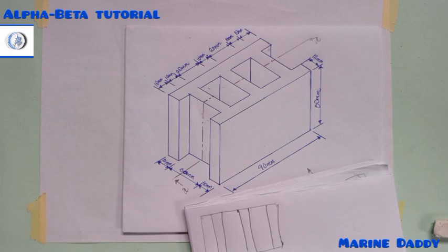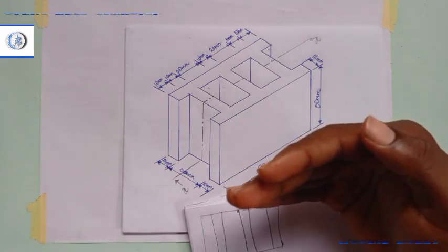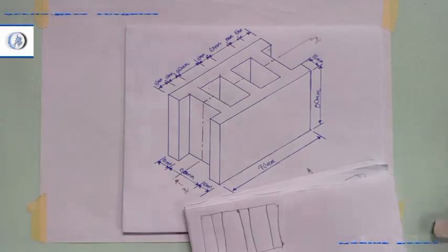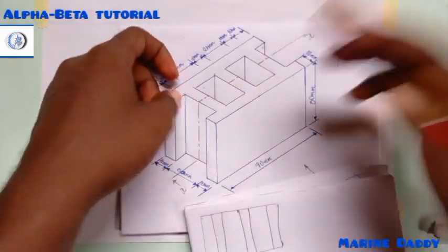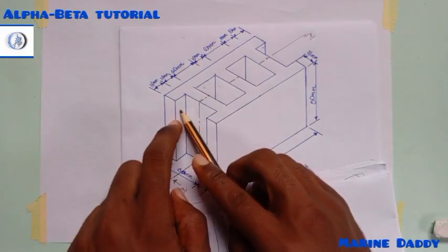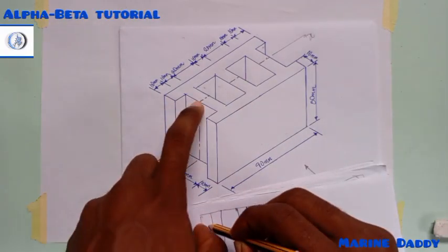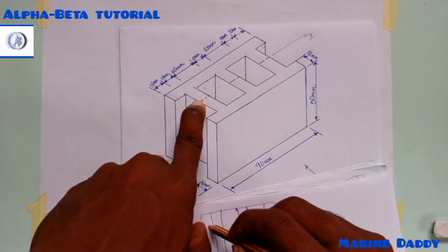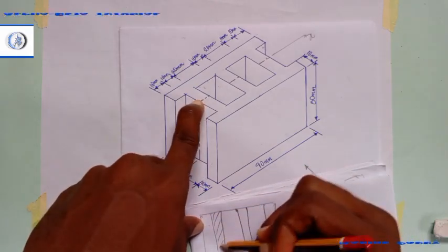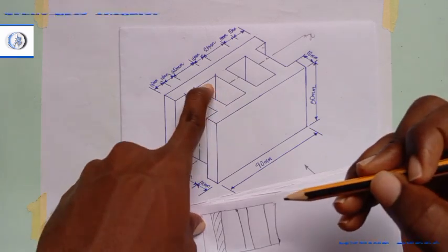Remember, we have rough edges and smooth edges. Rough surface and smooth. Okay, that means that the rough surface is going to be represented by the diagonal. Where is the rough surface? The rough surface is the part that is affected by the cut. Was this affected by the cut? No. Was it affected by the cut? Yes, here will be rough. Down. Was this side affected?